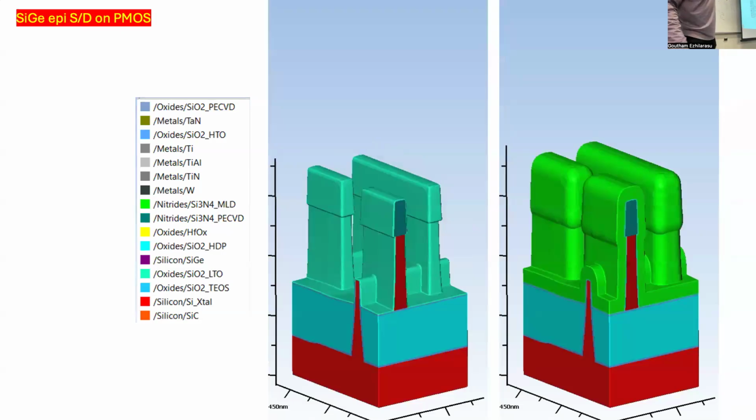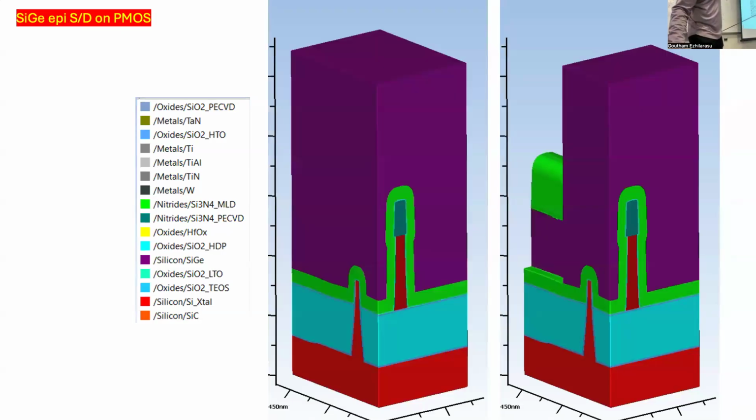Yeah, so basically, you put the oxide and then you put the nitride, and then you have a mask because you want to open one side, because one side you want silicon germanium, the other side you want silicon carbide, correct? Remember, this was the NMOS fin, and the PMOS fin is sitting in the backside, right? So the PMOS fin is going to be silicon germanium, the NMOS fin is going to be silicon carbide.